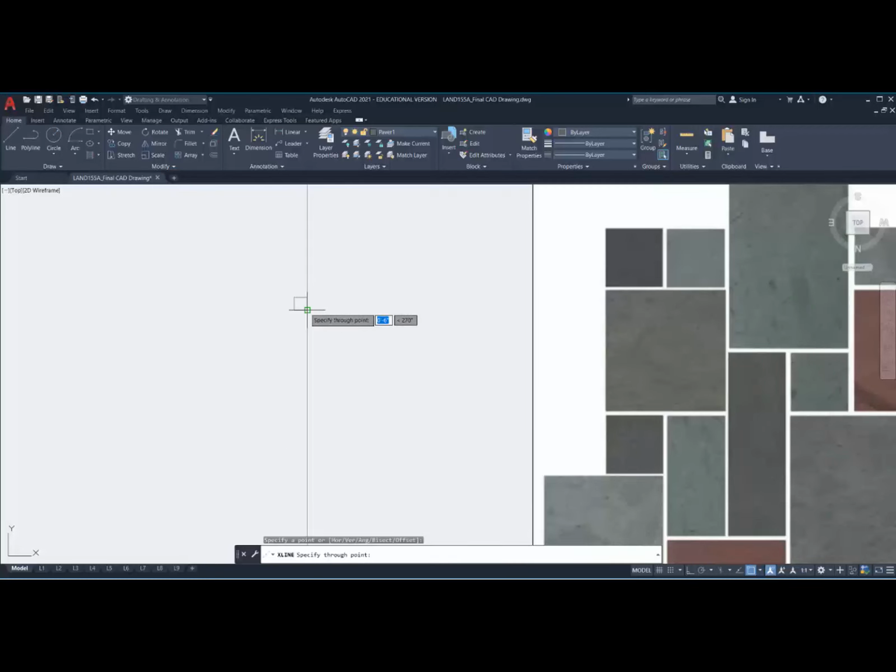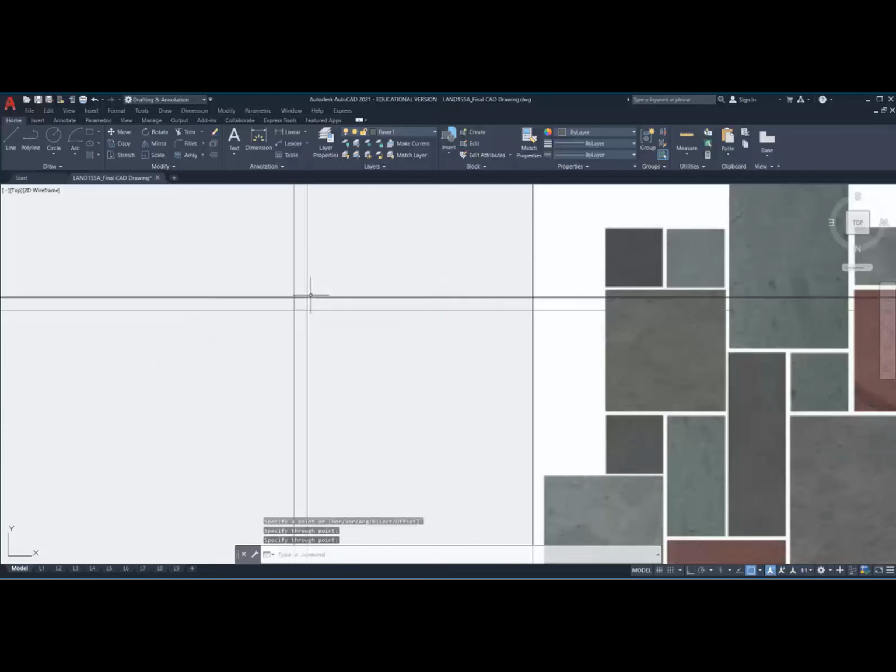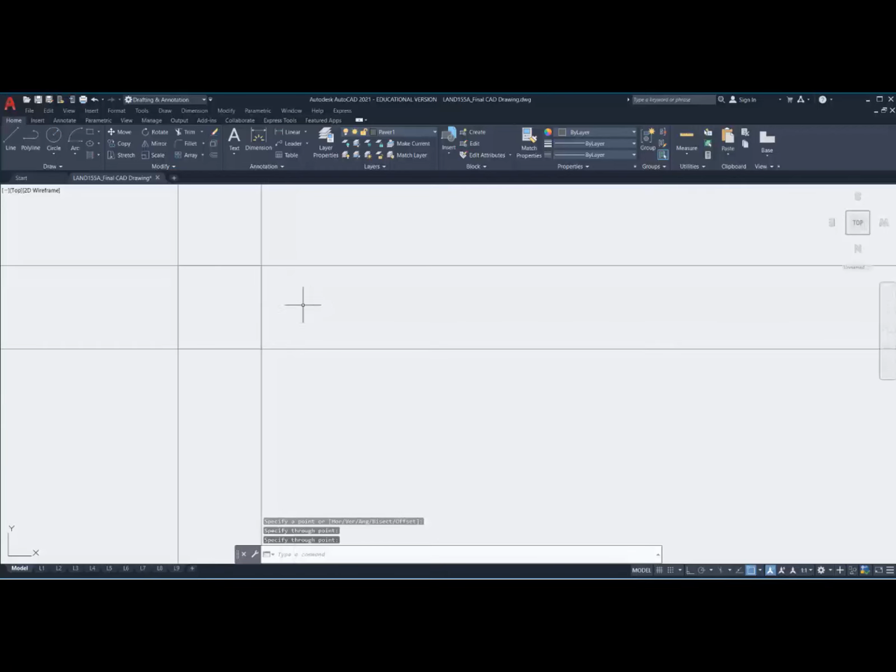But before I do that, I'm going to make a very accurate grid, and I'm going to use the construction line tool and select the four sides of the 6x6 grid. And now I'm going to determine what my grout spacing is. In this particular installation, the manufacturer suggests a 1/4 inch grout dimension. It's the way the tiles will lean up against each other. They'll allow for a 1/4 inch grout line, so that's 0.25.